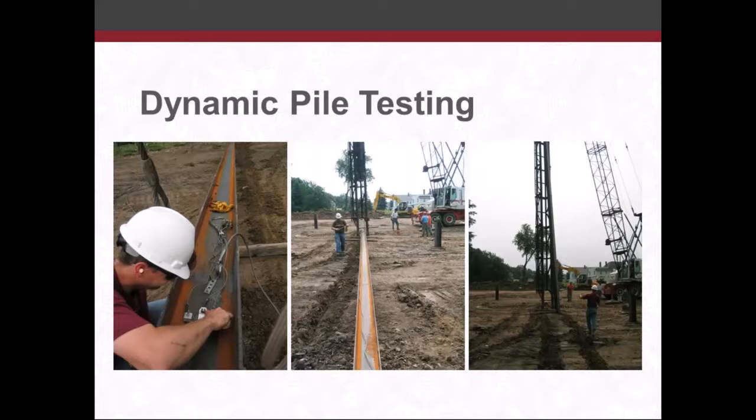And just some of the photos of the setup that goes into it. You can see attaching the sensors, and then we have the cables. Nowadays, the equipment is wireless. We can still wire as well, but we have Bluetooth capabilities, so we don't need these wires. And then everything is pulled up into the leads, and the pile's tested from there.